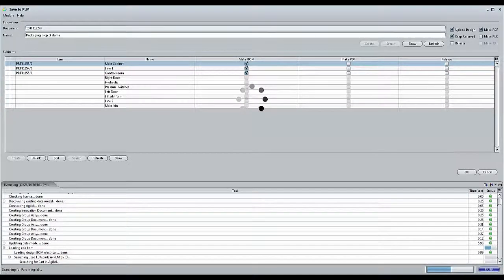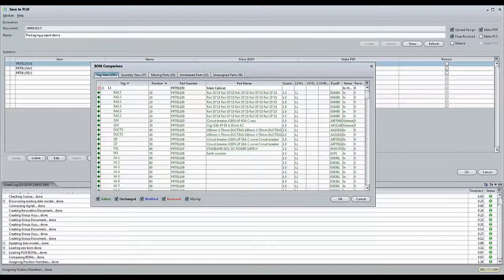Integrate starts reading the BOM from the design, and it checks for parts using BOM in Agile E6. It sorts the BOM according to some criteria, in this case the part number, and now it shows a comparison report. The report shows which parts will be added to the BOM in PLM and how the BOM in PLM will look.